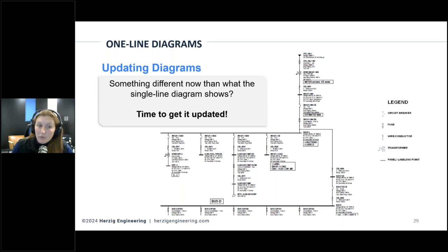We still look at them, we still verify them, but you don't end up necessarily having a different hazard result unless you're putting in a transformer or a different motor, a larger motor, or if you're having to refeed equipment and it's a super long run now between the protective device and the equipment, because that can have extra impedance and cause the breaker to trip slower, and so maybe it actually does need to have its specific calculation and update. There's a lot of factors to it, and I feel like I'm talking in circles, but I hope that helps get you on the right track if I answered the question the way that I read it.